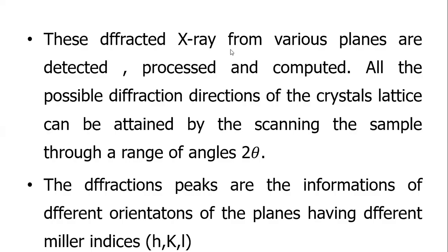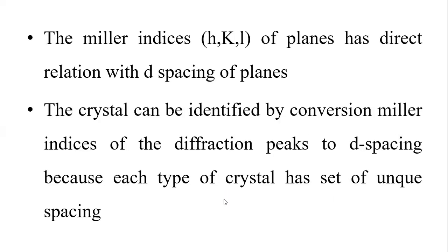These diffracted X-rays from various planes are detected, processed, and computed. All the possible diffraction directions of the crystal lattice can be attained by scanning the sample through a range of angles 2 theta. The diffraction peaks give information on different orientations of the planes having different Miller indices hkl.